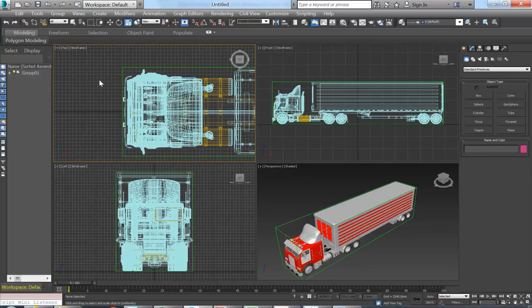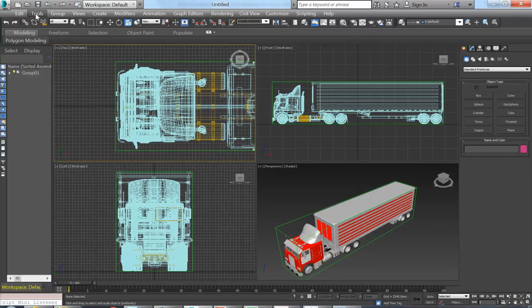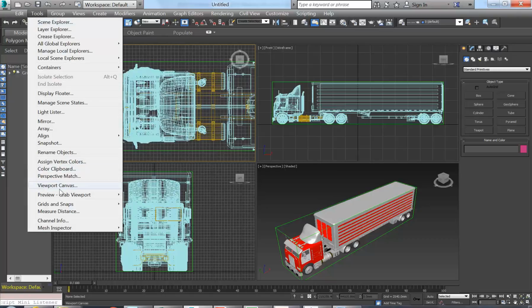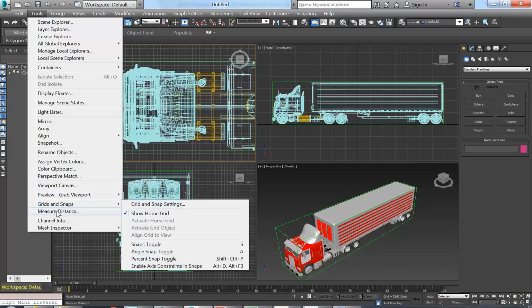I'm just going to do another one to check. So, do you know the width of a car? How wide is a car normally? Well, how wide's a car space? You should know that one. A bit more than 2, yeah, 2.4. 2.4, 2.5. Okay, so that's a dimension. 2.4 or 2.5 by 5.4 is a standard car space, which you'll need to remember for design.